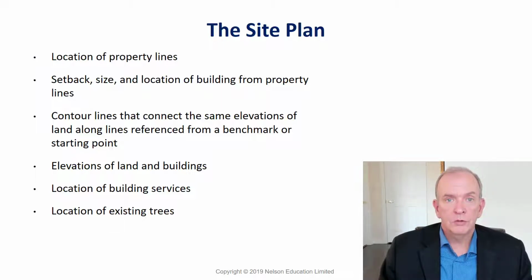If you cut down a tree that's over a certain size, there are usually pretty large penalties, some in the range of $15,000 to $20,000 per tree. And maybe for a particular purpose you have to cut down a tree. Then usually you have to pay the city a certain amount, and that has to tie into your landscaping plan of how you're going to provide new trees on that particular lot.